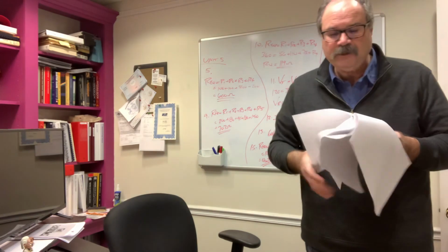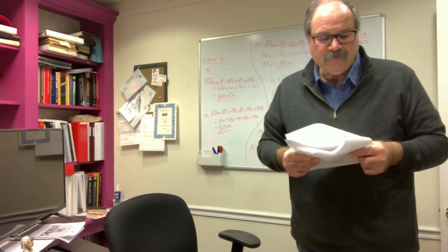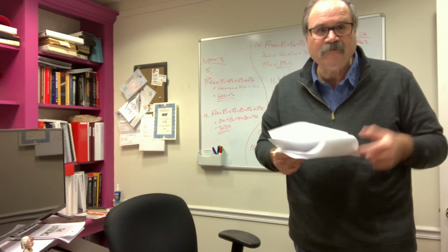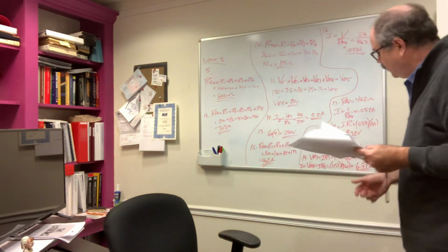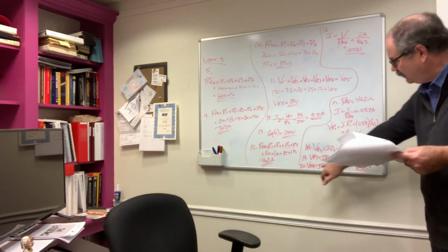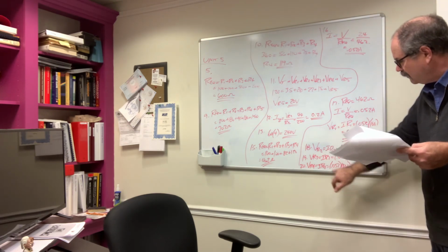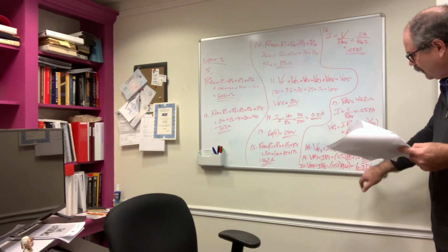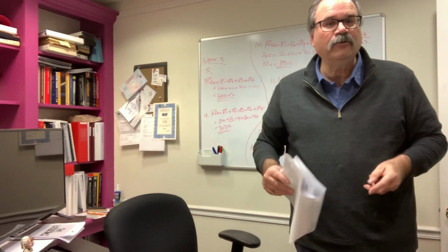And then the last question, question 20. Series circuit again, 4 resistors, 160, 100, 82, and 120 ohms respectively, connected to that 24 volt supply. This time we want to calculate the voltage across the 4th resistor, so VR4, same current of 0.052 amps multiplied by the value of R4, 120 ohms. Voltage drop across R4 is 6.22 volts.